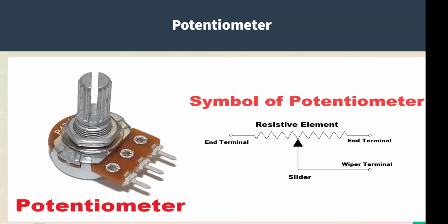When we talk about a potentiometer, that's what a typical one looks like. That one happened to be a PC mount type. It consists of 3 terminals. You have the 2 end terminals. Say that was a 50,000 ohm potentiometer. It would measure 50,000 ohms between those 2 end terminals.